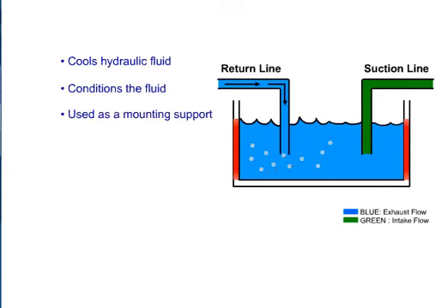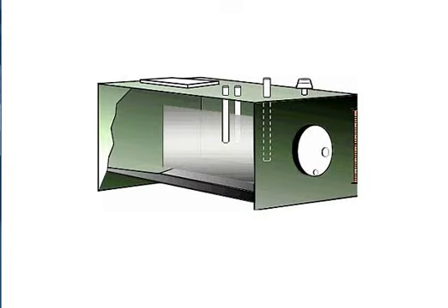The reservoir may provide mounting support for the pump or other components. A well-designed hydraulic system always includes a properly designed reservoir. An industrial reservoir should include the following components: a baffle plate to prevent returning fluid from entering the pump inlet,